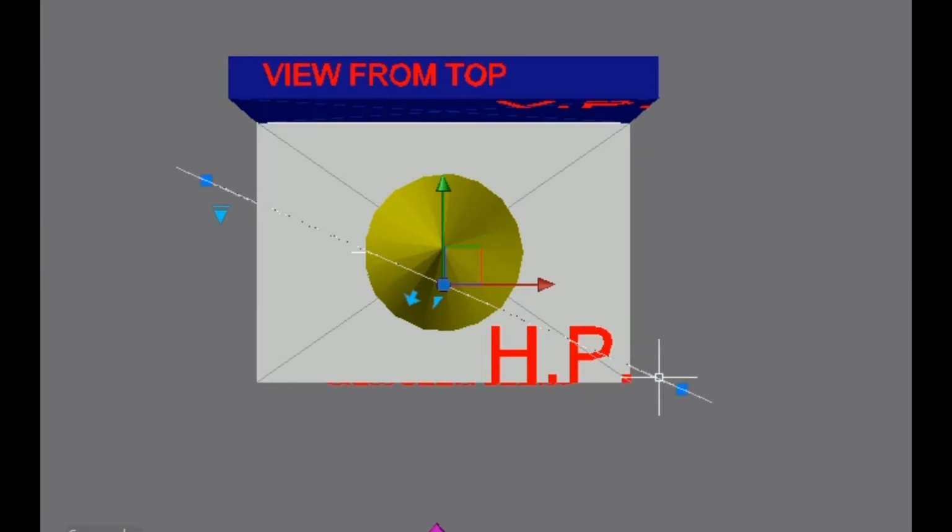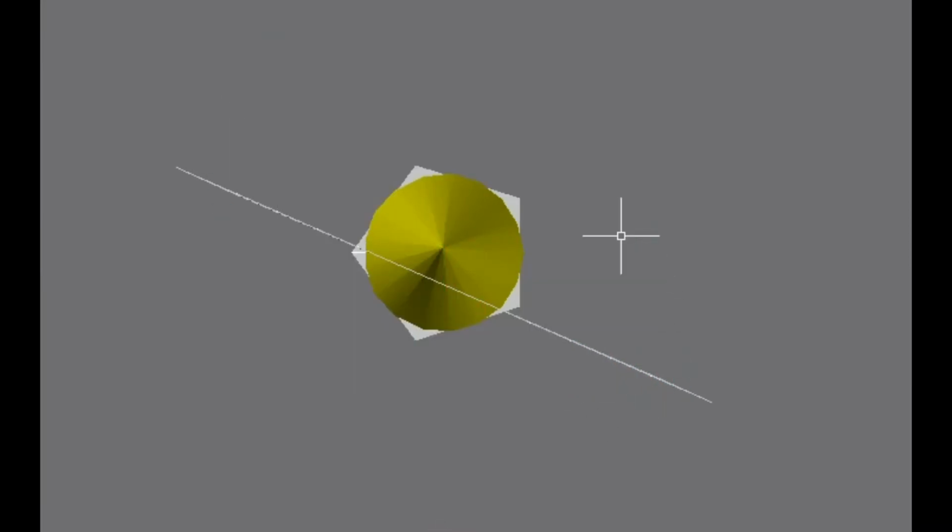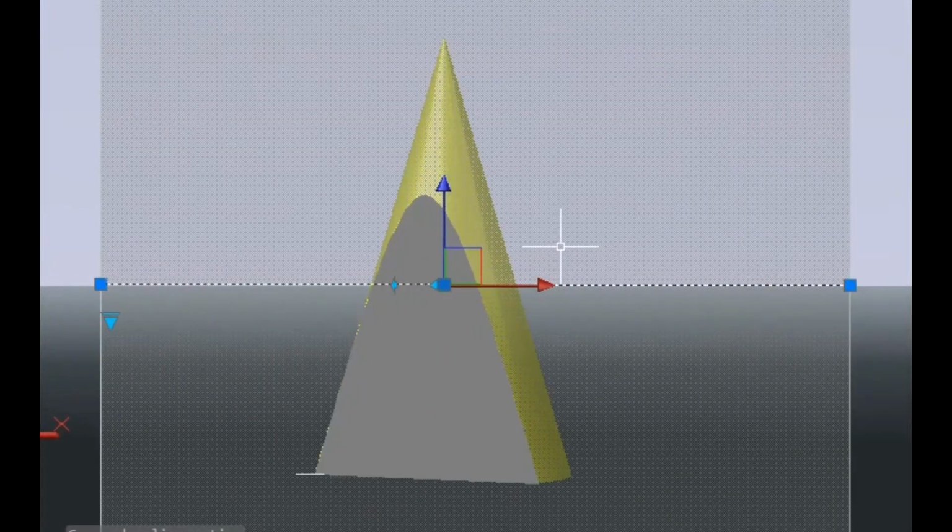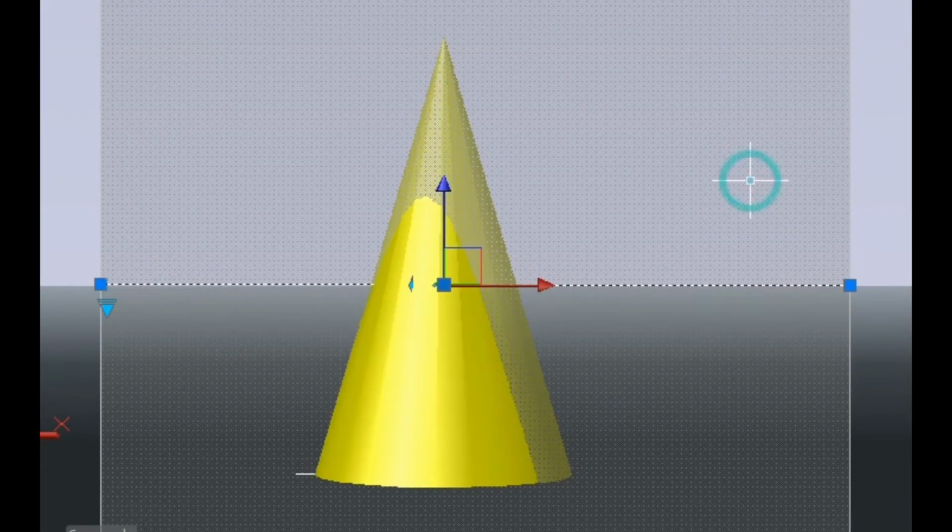And from the top view, you will see that some portion of the circle will be removed, and I have erased the planes. Now you can easily imagine this. So this is going to be our final top view, and this is going to be your front view. Some part of the circle is removed, and in the front view there will be an ellipse. But also we have to draw the true shape from this axis. This is going to be our true shape because it is visible from this side.